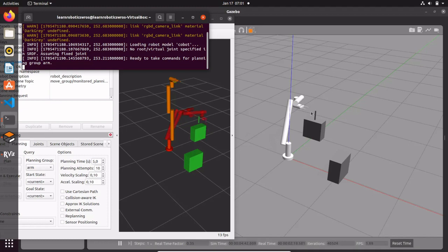And as you can see, this is why I have decided to put the place position at plus 0.1 compared to the other, because if you have paid attention, when you grasp, it slides a little bit at a certain point, and since it will not pick at the center, if you don't modify the Z action, you risk that your object is going to hit the table.